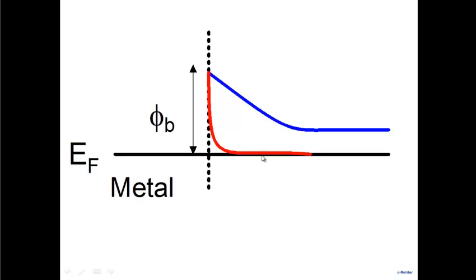And you can see here, conduction band is merged with EF. High doping means what? EF is very close, right? It's almost merging with EC here. So you have two pictures here. One is a low doped Schottky barrier diode, where depletion widths are large, and another one is a very highly doped Schottky barrier diode here. So now let's see what happens as a result of doping.